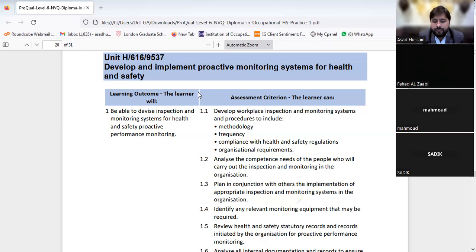You mean the records or the results from that monitoring can be attached at this point? Yeah, absolutely. Like you have a dosimeter placed there, and you have different results. For example, we have a noise meter when we are making the noise inspections, and we inspect from different places, and even at different times of the day. The results will be different. So you can attach a result like that, and that will be enough for me. Okay.